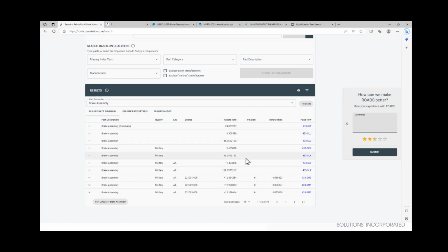And there are a couple of other spurious failure rate quantification factors that could be involved. But C means cycles, M means miles, which is important, especially for ground mobile stuff. If you look up a connector in the EPRD, you might see its failure rate in million miles.